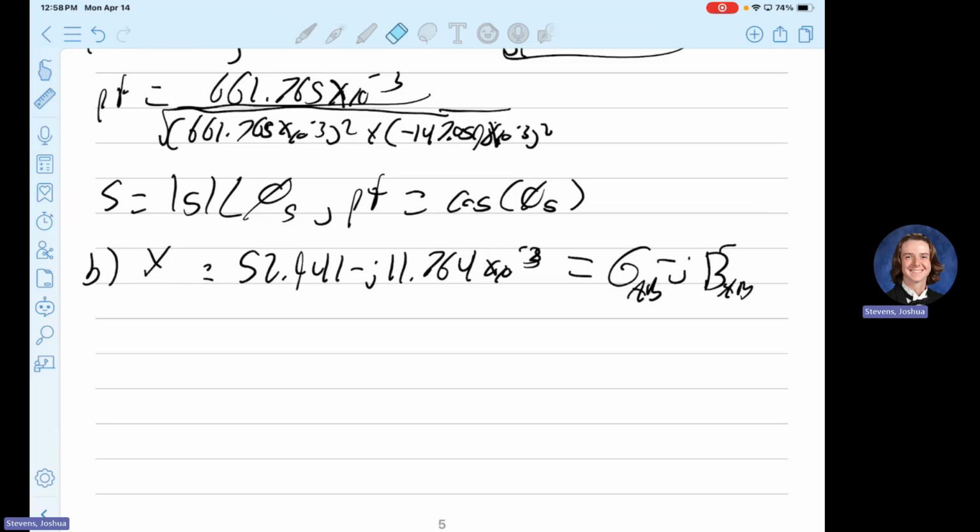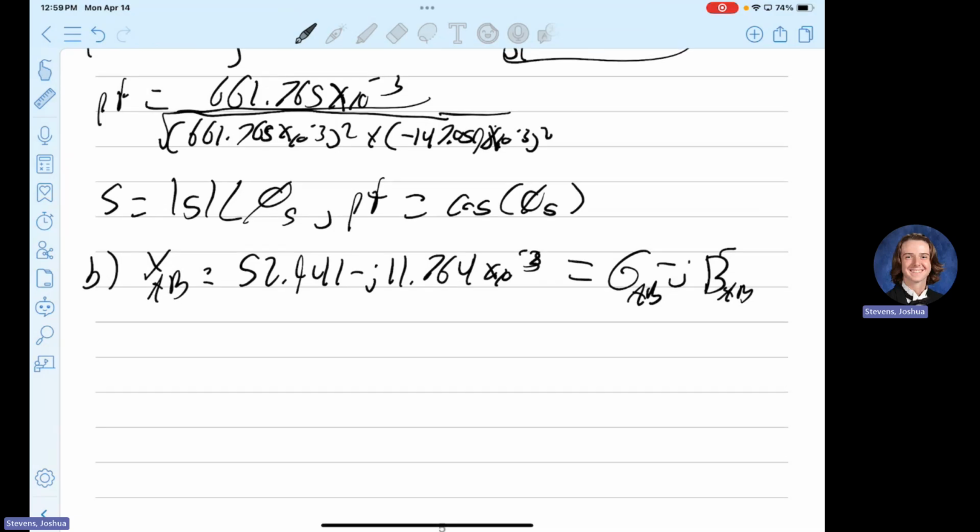This is YDP. It's also called YHP. It's basically the input. So we have a negative susceptance. Can anybody tell me what type of equivalent component that is? You said something about an inductor and a capacitor. Those are components. Which one has a negative susceptance?